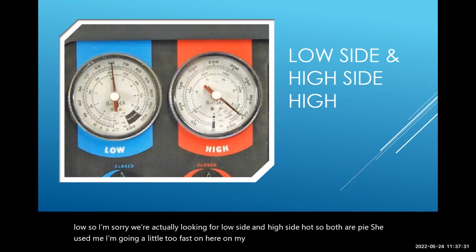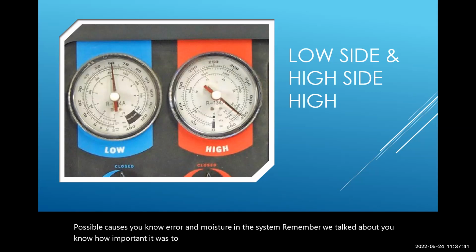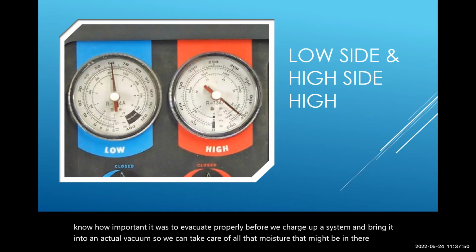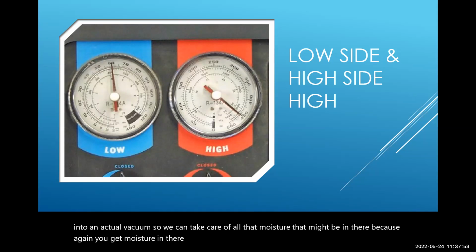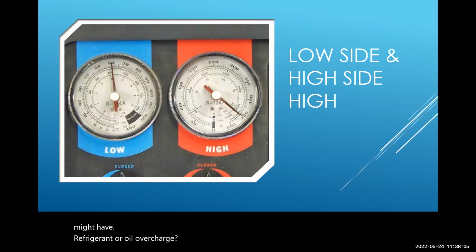Possible causes, air and moisture in the system. Remember, we talked about how important it was to evacuate properly before we charge up a system and bring it into an actual vacuum so we can take care of all that moisture that might be in there. Because again, you get moisture in there, which causes all kinds of problems. Also with air, if we have air in the system, it can cause the pressures to go all over the place. And then we might have a refrigerant or oil overcharge, and that's a possibility.